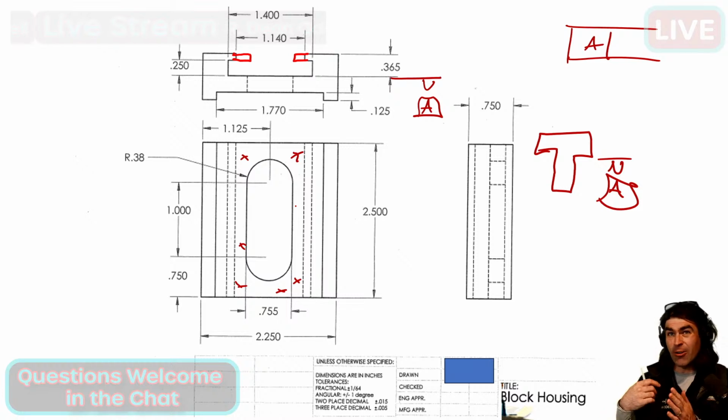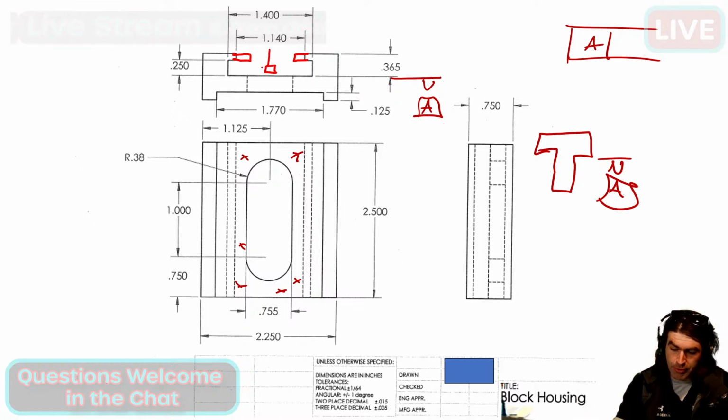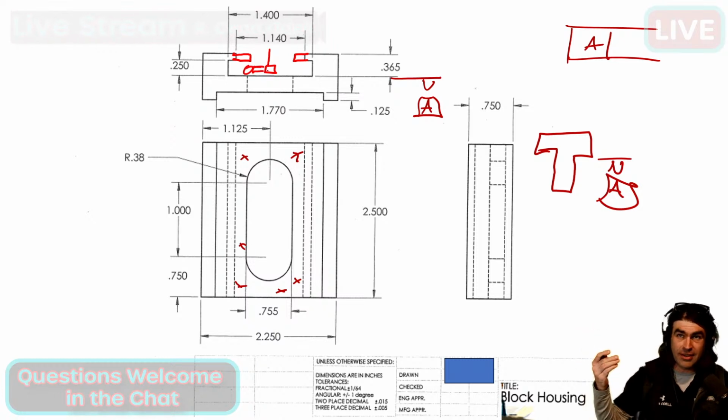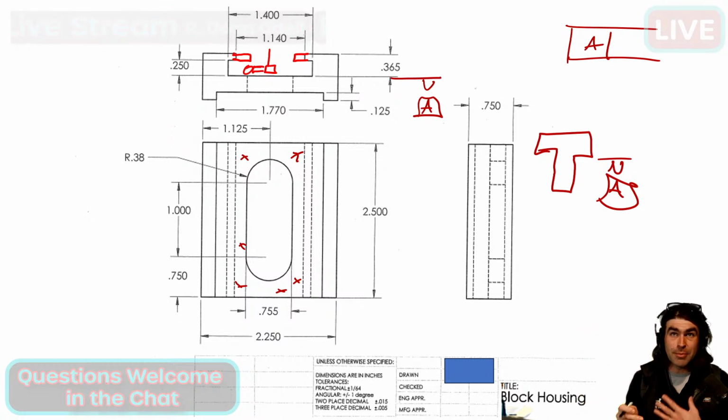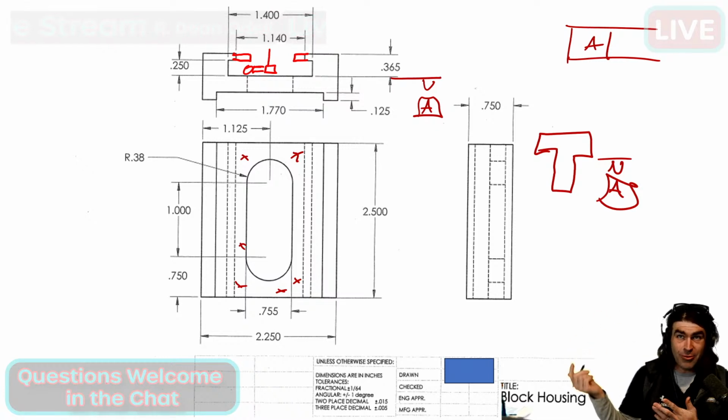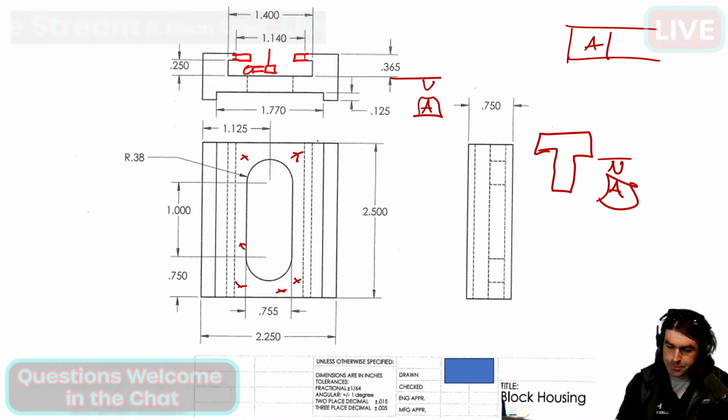Now they make all kinds of funny probes. You could say, oh well, I'll just get a custom probe that goes in sideways and does it. But then you've got to buy that, right? And then you've got to spend a bunch of time qualifying it, and make sure your qualification's right, and preferably you want to be able to just get it with a regular probe. If you're a CMM expert, feel free to chime in if you disagree with me. This is kind of how I see things.